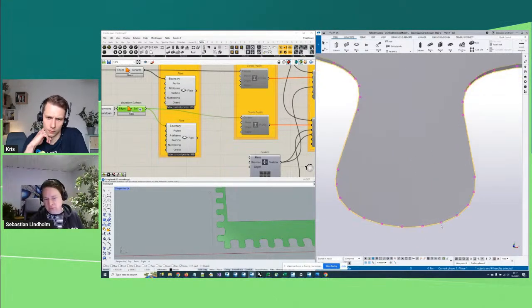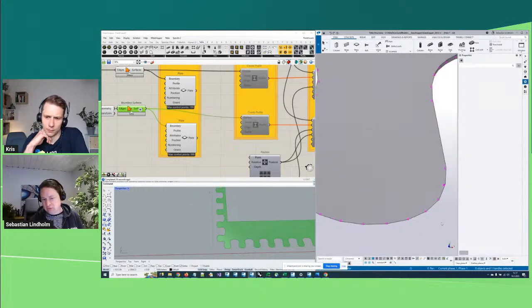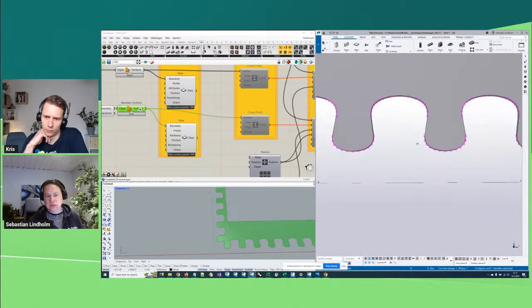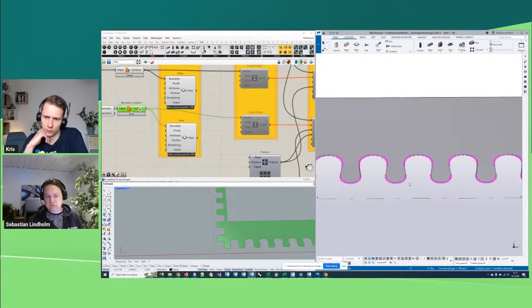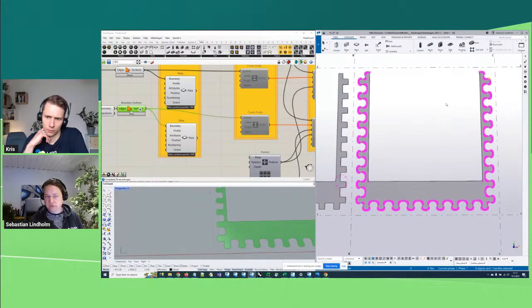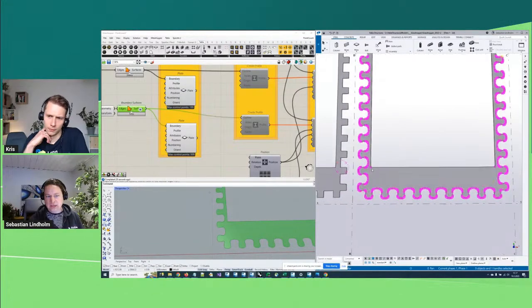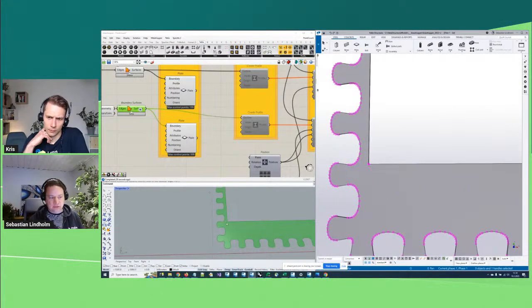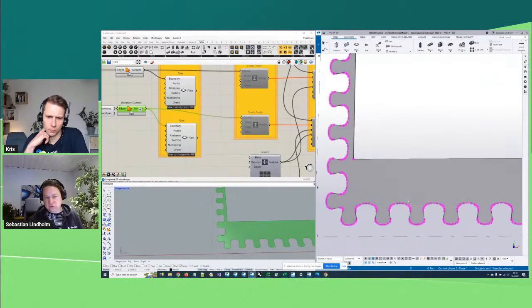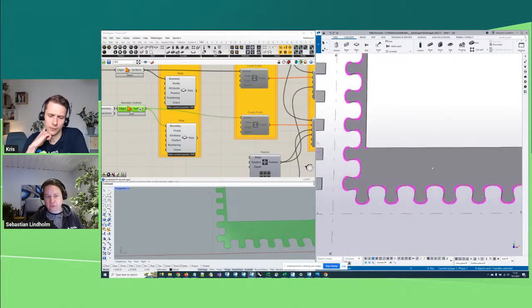But if you really zoom in, even though these are round, it will still be jagged, and that's just the way Tekla works. So for practical purposes, these are round, but in practice you have hundreds and hundreds of control points. It does keep the actual control points, the sharp corners, in place. But for the curved parts, it just tries to estimate using a maximum of 999 control points.